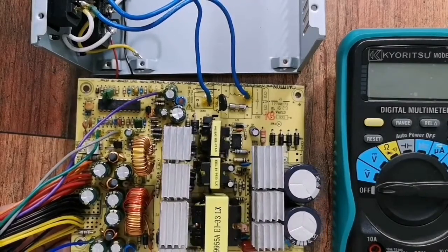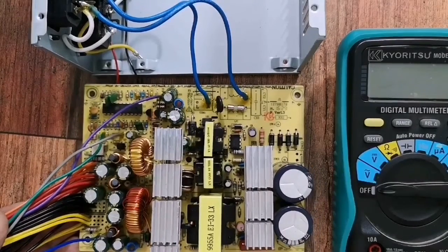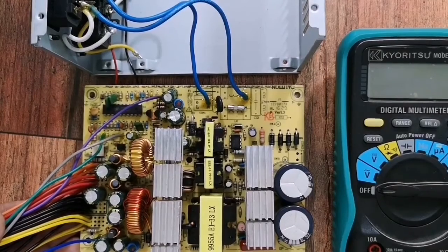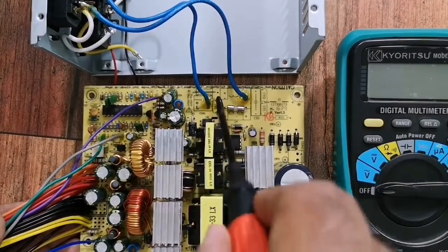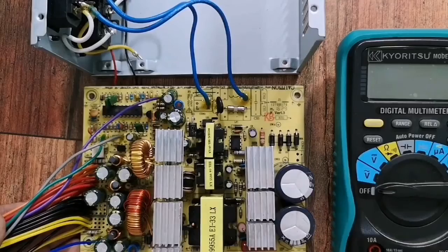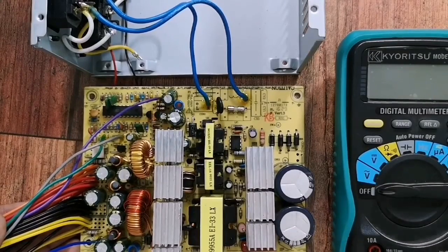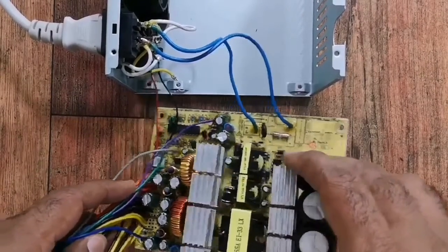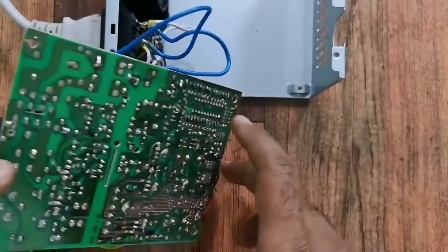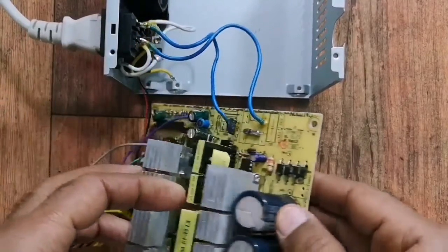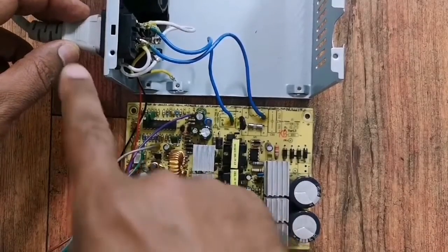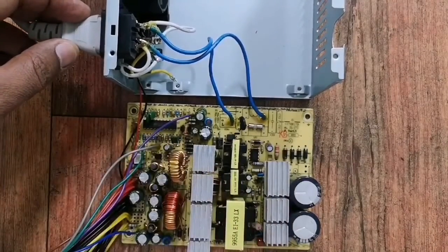Once you locate the shorted component, replace it, but keep in mind to check that the short may be caused by another failure in the circuit, which is connected in the same loop. In this circuit, I checked and I could not find any shorted part. Therefore, at this step, I will need to continue the troubleshooting while the power is on.